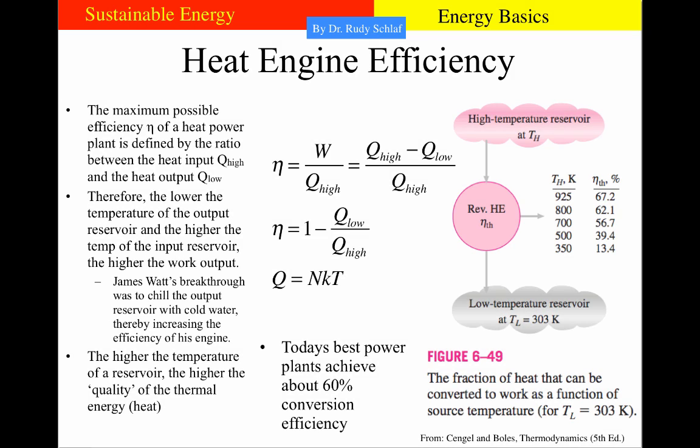Let's see what determines the efficiency of a heat engine. So efficiency here means how much of the heat that we put into the process at the high temperature reservoir is actually being converted to work, and how much of that energy is going into the low temperature reservoir. Now, if we just consider the heat that comes in and the work that goes out, the efficiency is just the ratio between work out and energy in on the hot end.